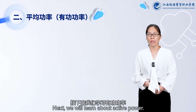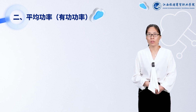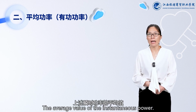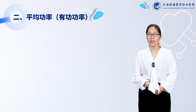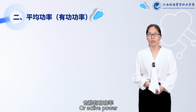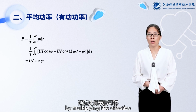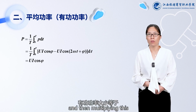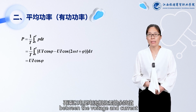Next, we will learn about active power, or the calculation of average power. The average value of the instantaneous power is known as average power, or active power. It is calculated as follows: multiplying the effective voltage and current values, and then multiplying this by the cosine of the phase difference between the voltage and current.